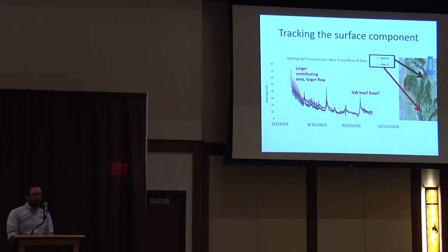One of the most important things we can do is measure how much water is moving through the creek. This is going to tell us, upstream and downstream of the diversion, how much water is getting taken out of the system and is effectively in the system at the bottom of the watershed. On the right, I'm showing you again the smaller map of the Spencer Abbey Wilderness Habitat Management Area. Flow is going from top to bottom, and we have two stilling wells. A stilling well is just a place where you can put a pressure transducer so you can measure how high the creek level is at that point.